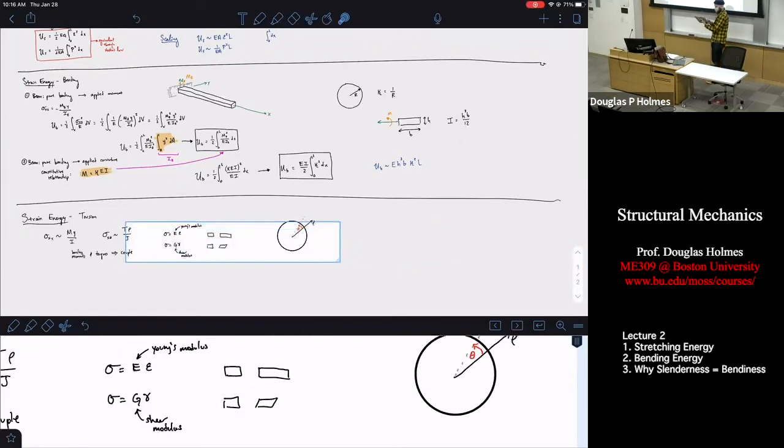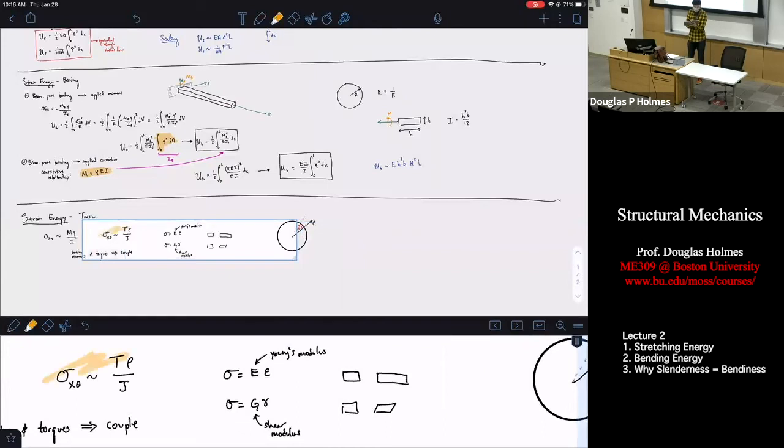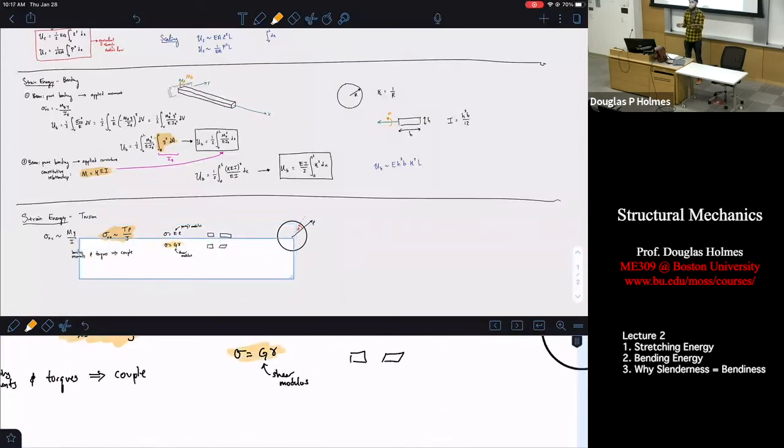This is mostly a refresher to tell you that your Young's modulus is also the same. It's saying there's a linear proportionality between stress and strain, where in uniaxial extension, this is just like how you keep the same shape, but elongate or change its area. And shear modulus is kind of keeping the area the same, but distorting the shape. This is a very long-winded way of saying that here's our stress, which looks very much like the stress that we had before. Here's our Hooke's law, which looks very much like the Hooke's law we had before.